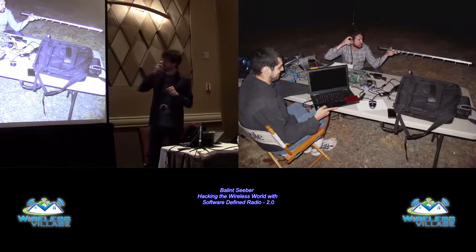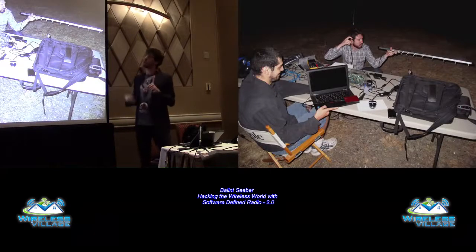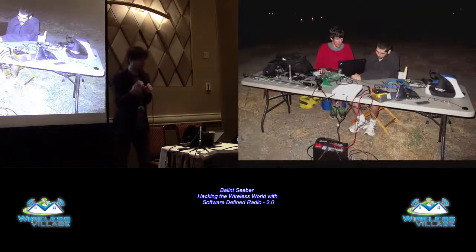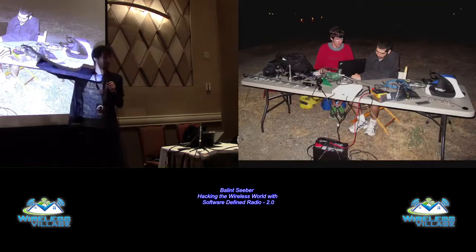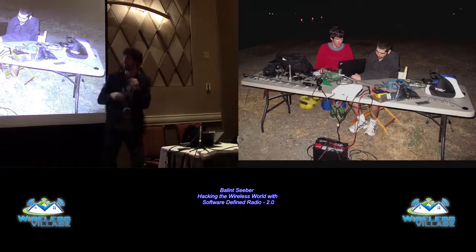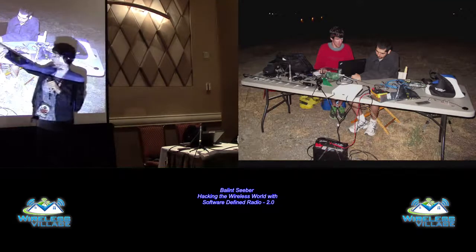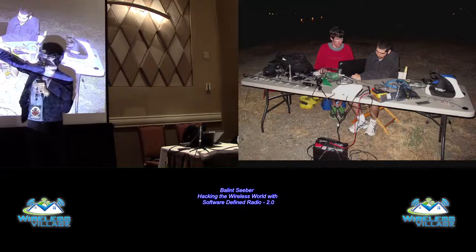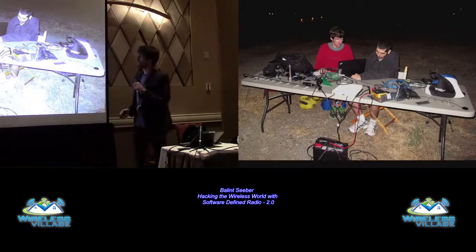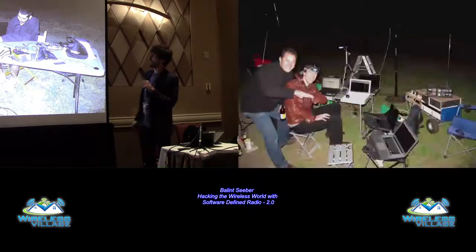But some of my friends and I went up there last Friday to try and collect a little bit more data. You see we've got the antennas out, and they were really nice in terms of sacrificing their hand, because unfortunately the Thunderbolt connector on my laptop died, and the only way to make it work is if you push the Thunderbolt plug-in with all of your might. And that was actually hooked up to a PCI Express adapter box, which had a 10 gigabit Ethernet card in there that was then hooked up to an X300, X310, so we could sample at 100 megs a second. And it's all powered off a battery there, so it was a bit of fun.